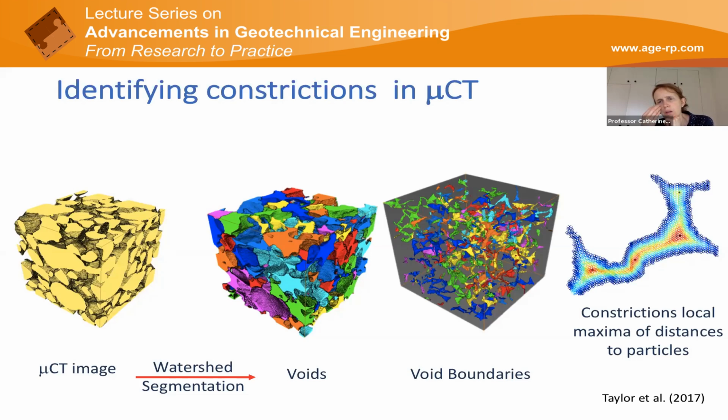So normally, I presume this is for DEM, when we're creating very loose samples, we use a high coefficient of friction. And sometimes we make a sample and we isotropically consolidate it, and the minute we start to try to pass a shear wave velocity through it, or to shear it in a simulation of a triaxial compression test, it collapses.